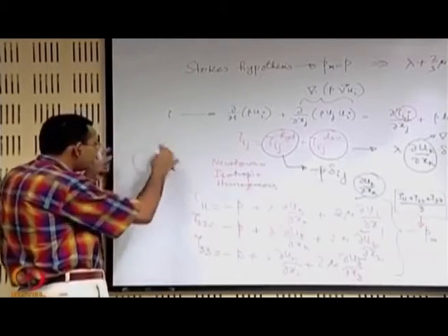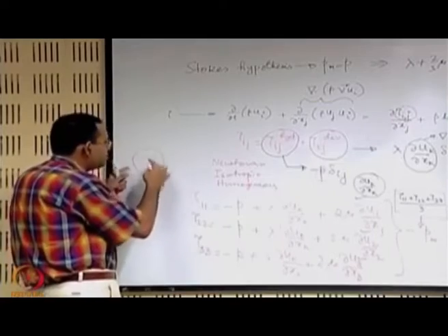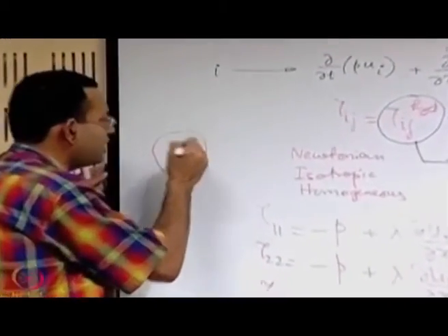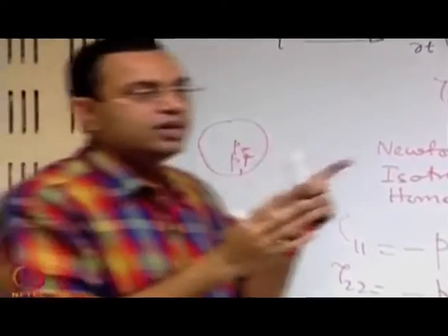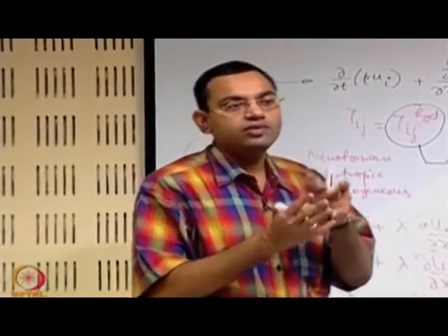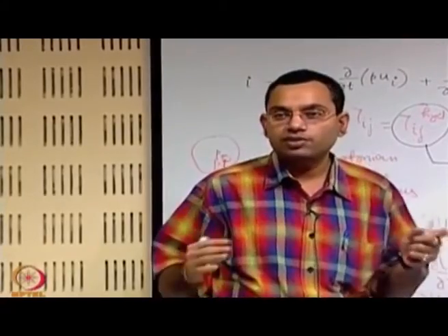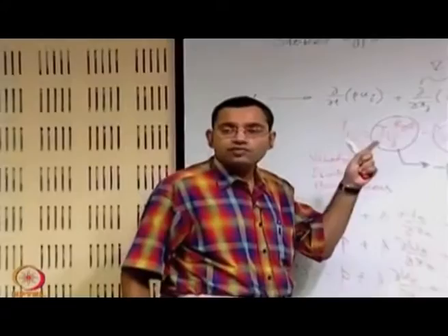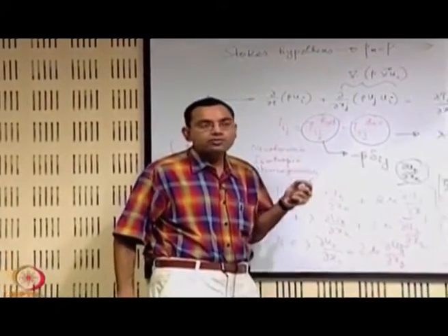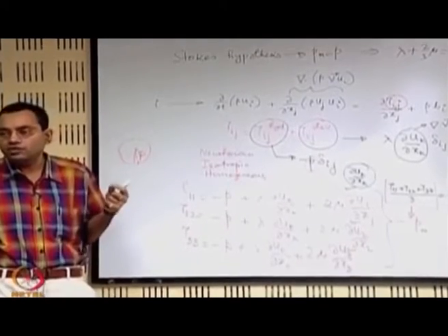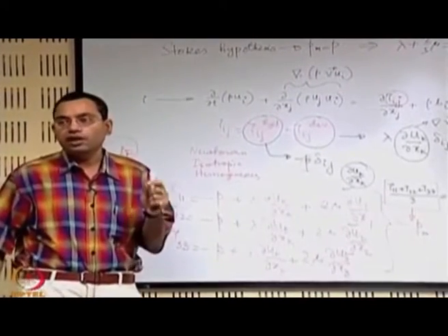It is not a global equilibrium, that means it is not that throughout the system at each and every point properties are the same, but at each and every point at least it attains an equilibrium where its properties are related by the equation of state, and eventually the interconversion from one mode to the other is possible, that time is available, and that is why Stokes hypothesis works for most of the problems. Only for a few rare cases where the change is so rapid in terms of the time scale, there it may not work, otherwise it is working.